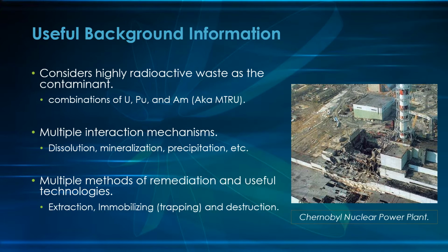But nonetheless, most examples can be divided up into main categories such as extraction, or the physical removal of the contaminant; mobilizing, which doesn't actually remove it but just prevents it from spreading, it's still in the ground; and finally destruction, which destroys it in situ, but it probably leaves some residue behind. So those are just some of the main useful background information you should probably keep in mind.